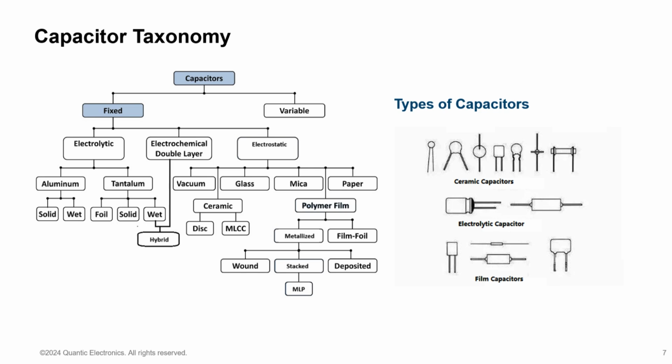Electrostatic capacitors are a more classical example of a capacitor. They're very simple in theory. They can consist of two or more capacitive plates separated by an insulator or dielectric material. That material is a defining factor of the capacitor type. It can be anything from free air, glass, paper, plastic. These are similar choices to what you have at the checkout line, right?